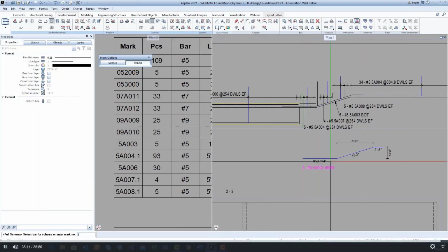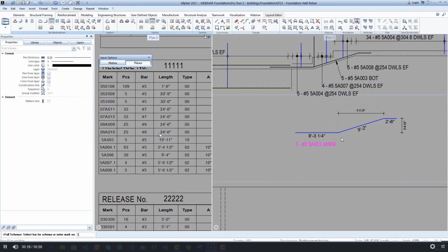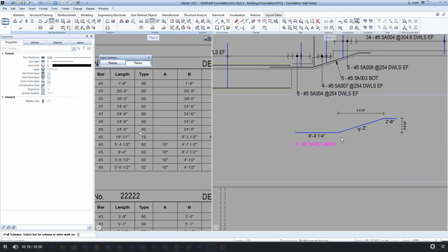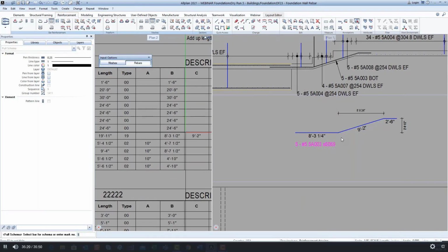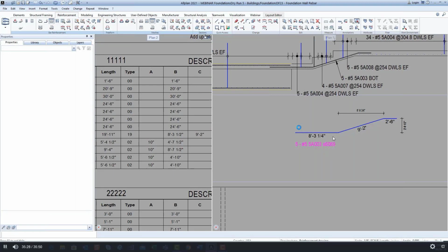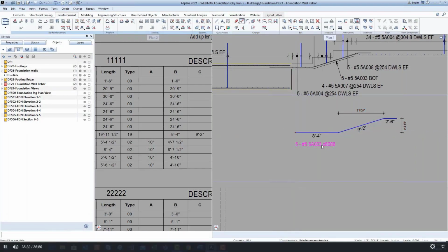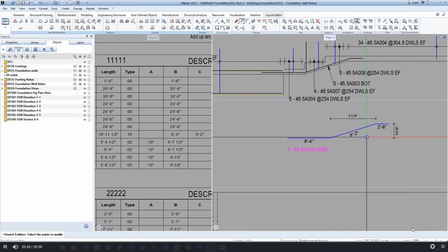So one last thing I want to show you here is pulling up data from a bent bar, and how pulling out what we call the schema of that bar will allow you to change the bar again. Everything is linked, so not just the information, the number, but also the data behind the bar. Now I stretched it first here. I didn't quite stretch it enough to make a full change. I meant to stretch it 3/4 of an inch instead of a quarter, but I'm going to stretch it. You'll notice here that I've got changes here, and in my bar list, the update changes.